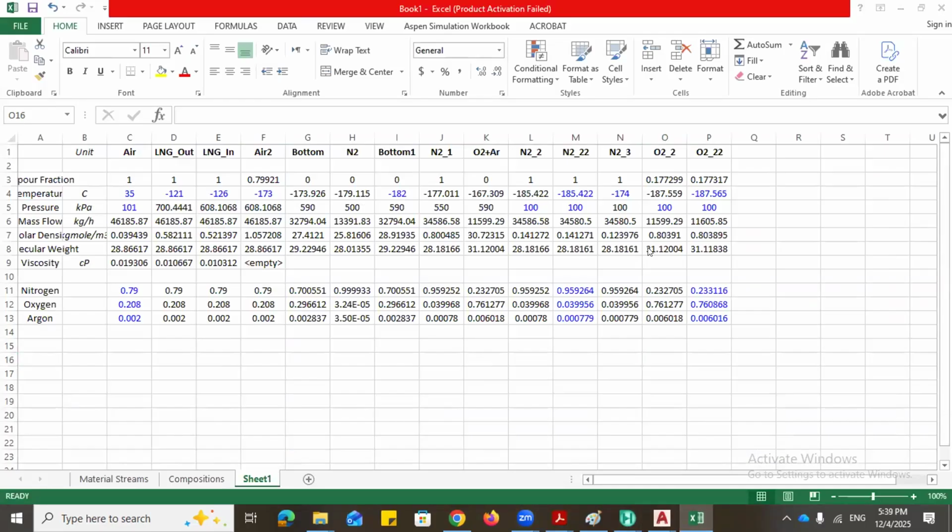I will need that class recording of the training materials, please. Okay. So this is the heat and material balance. This is the number one process deliverable you can generate from your simulation. Even when we are done with our field design, simulation aspect, because when we go to field design, we'll not just go direct and start doing our sizing. We'll first complete our simulation, because the conceptual stage of design, or conceptual studies, is there for you to develop the process scheme and confirm that you can produce this product with the feed from the scope of work that the client has given to you.